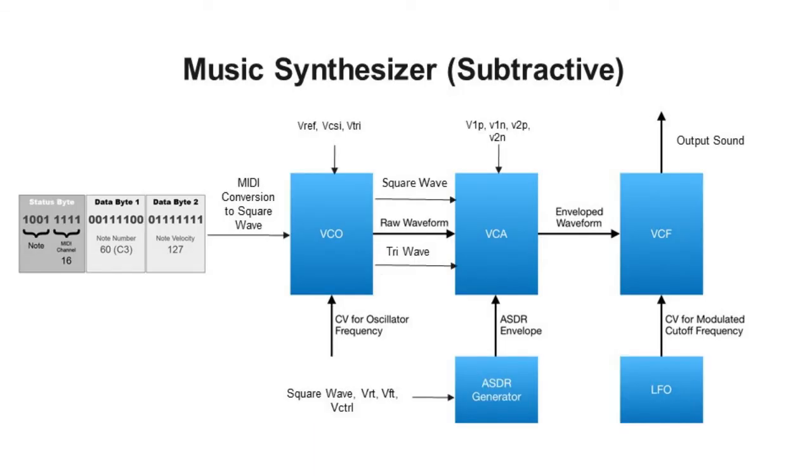Our original high-level approach involves sending MIDI information from a keyboard onto the FPAA's MSP430 microprocessor. The MSP430 would be programmed to convert MIDI data into a set of biases for a voltage-controlled oscillator, or VCO. The VCO would generate a square wave, triangle wave, and sine wave with the frequency of the note it was given. This waveform would be fed into the voltage-controlled amplifier, or VCA, which would modulate the waveform's amplitude with an attack, sustain, delay, release envelope, creating a realistic-sounding fade-out effect.